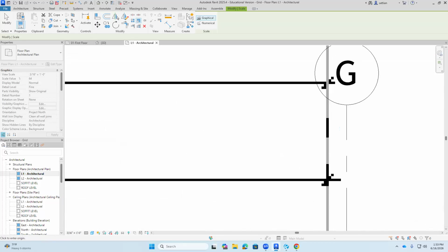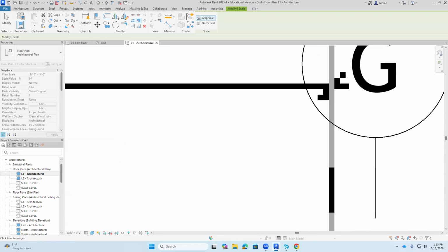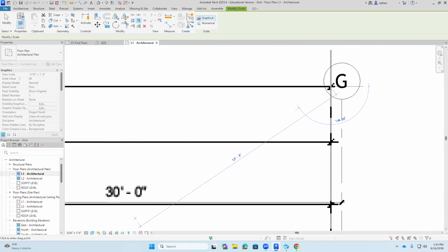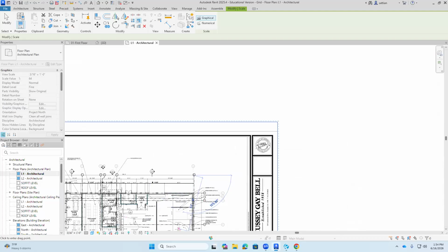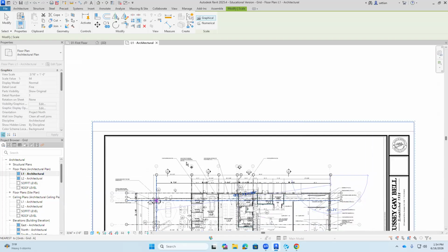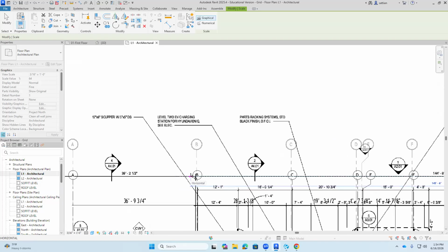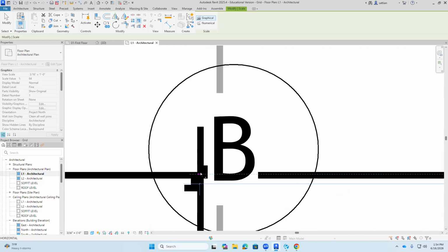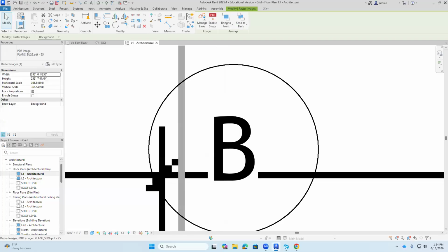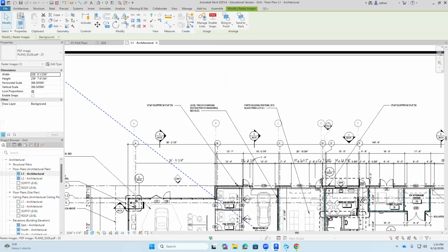144.8 goes from this point in the drawing, okay? And then go the other way up to grid line B. Notice I've not clicked again. I'm still in that edit mode. And then I'm going to scroll, come down here, get as close as I can to the middle of that, and then type in 144.8. Now it's resized.